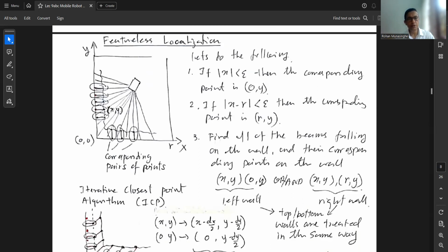Now this illustration shows you indoor localization, right? You can see the robot in the middle, and all these lines are LiDAR beams, infrared laser beams, right? And they hit on the wall, and robot measures the distance, right? You don't have to have all of these laser beams here. Maybe you can take every 10th, okay? You use the 0th one, then 10th one, 20th, like that. So undersampled set of readings.